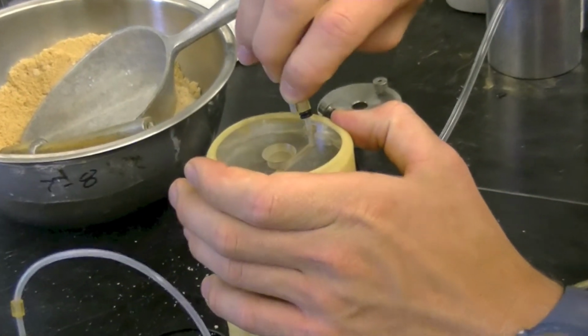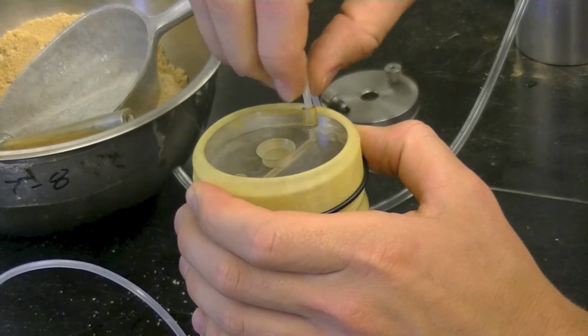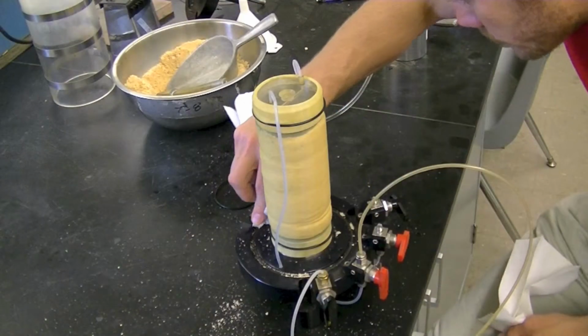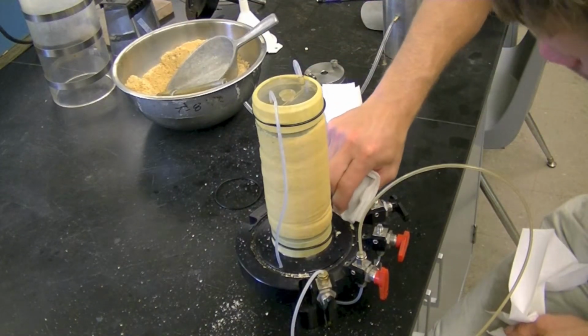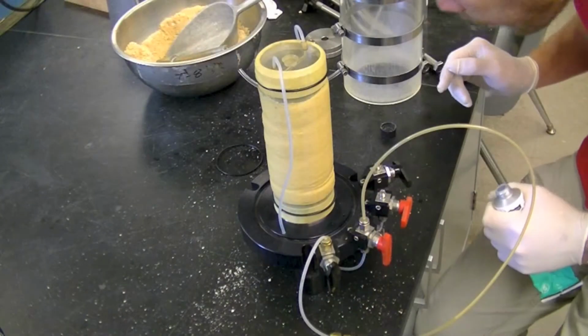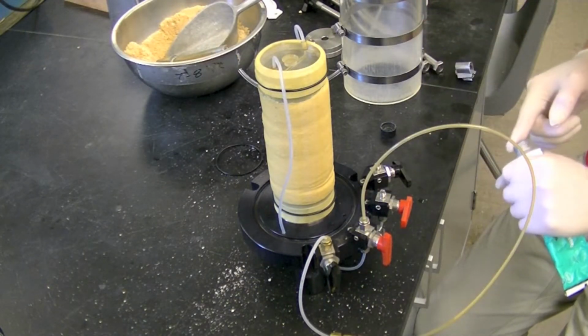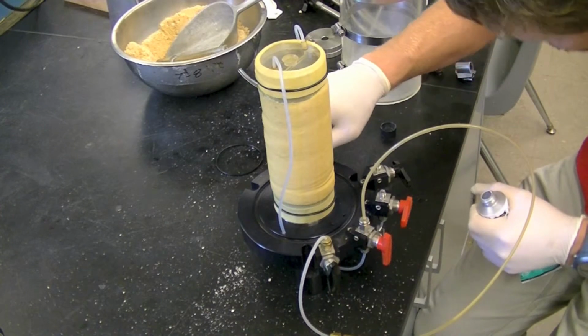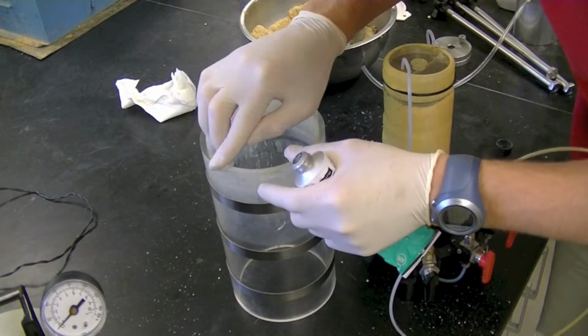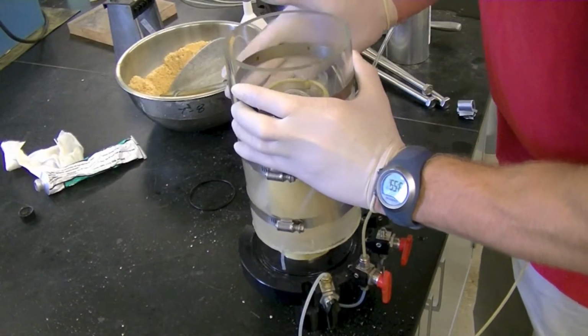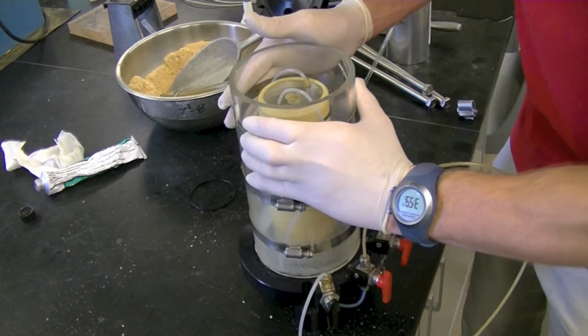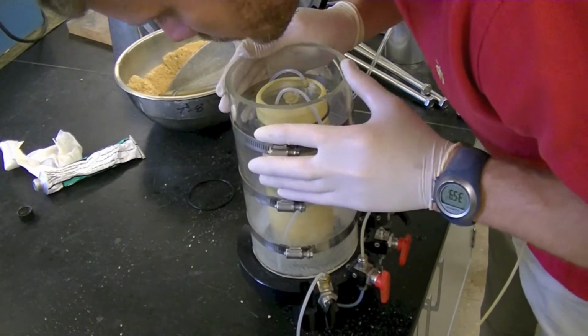Connect the drain lines to the top platen by pushing or screwing them into the inlets. Clean the base pedestal and wipe away any soil that may have spilled during molding. After the base is completely clean, grease the bottom gasket on the pedestal. Grease the bottom of the cell. Place the cell over the specimen and slightly turn it to the right to seat it within the gasket.